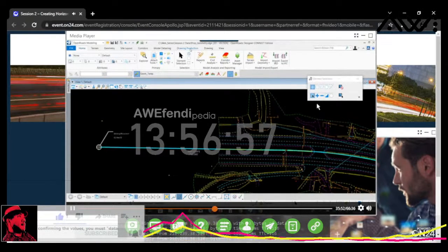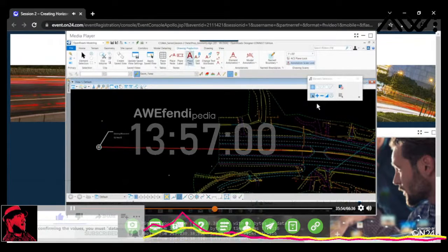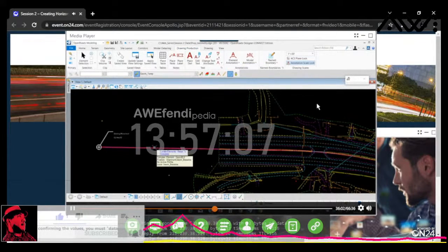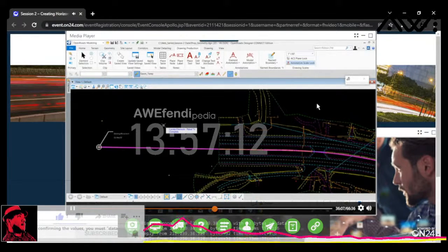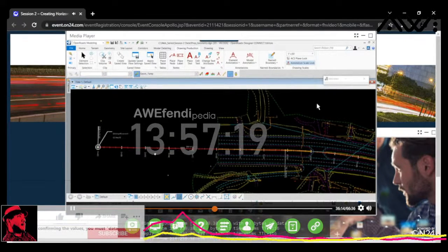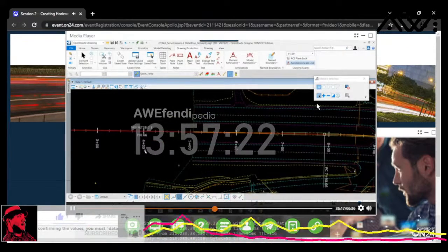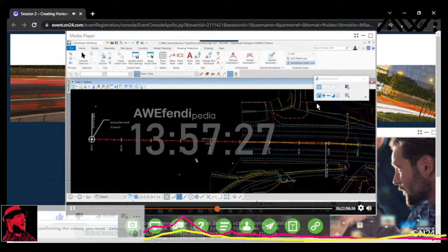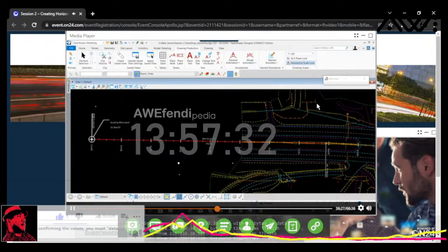So I can go up to Drawing Production, go to Element Annotation, select Annotate Element. I'm going to follow the prompt and select the actual baseline. Okay, left click to select it. I'll right click to complete the action. And so now you'll see the baseline's been annotated. You'll see the stationing starts at 0+00, and I want to make a modification to that. You'll notice in our report, this project's going to start at 500+00. And so we need to modify that start station to match that criteria.